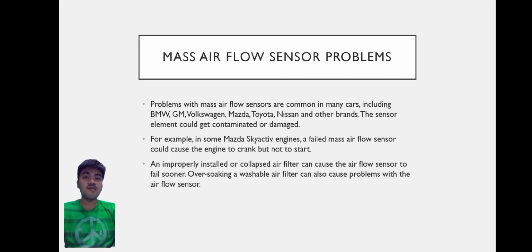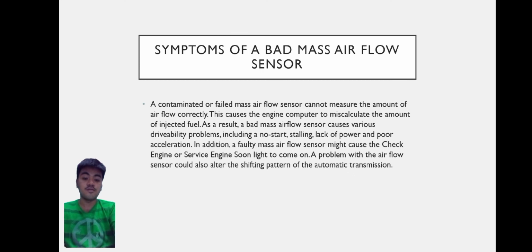For example, in some Mazda Skyactiv engines, a failed mass airflow sensor could cause the engine to crank but not start. An improperly installed or collapsed air filter can cause the airflow sensor to fail sooner. Oversoaking a washable air filter can also cause problems with the airflow sensor.